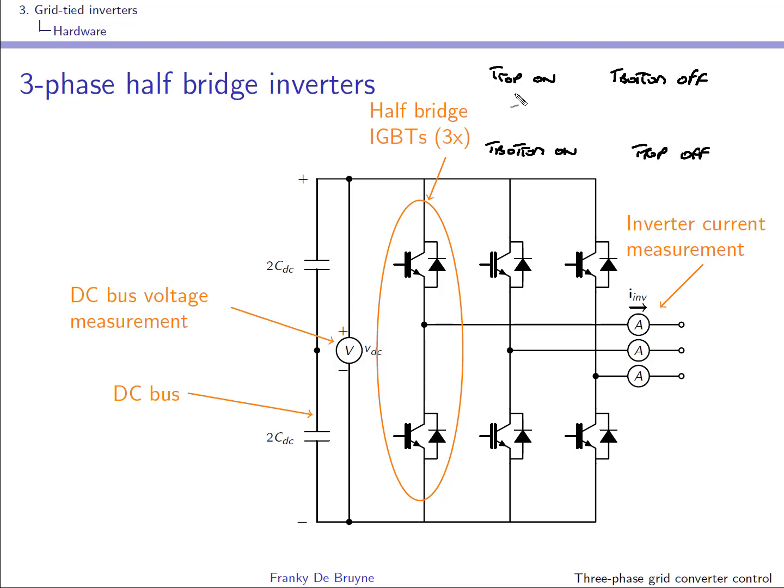So what you'll have to do is to go through an intermediate step, top transistor off and bottom transistor off. And this is what is called the switching delay.